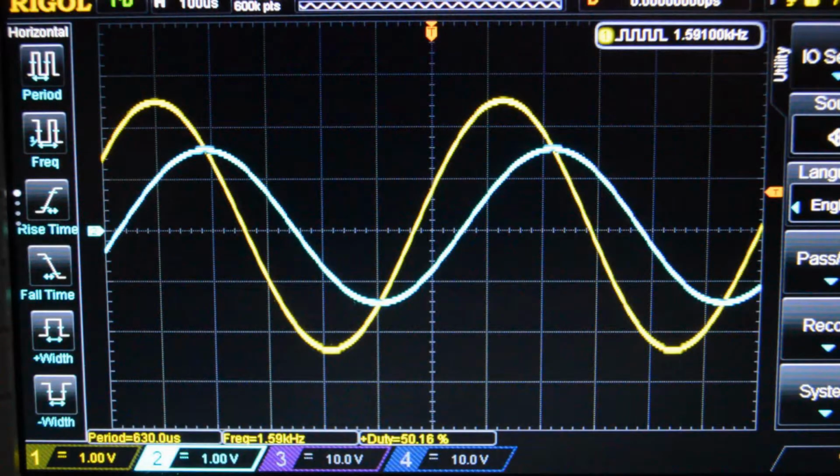If we compare the waveforms again, but expand our time base, at the break frequency we can also observe a phase shift in the output of approximately 45 degrees. Therefore, impedance is a combination of reactance and phase shift. The phase shift requires complex algebra and is not in the scope of this video, but rarely is cause for concern. In reality, the phase shift and amplitude are interlinked, and you cannot specify them independently.